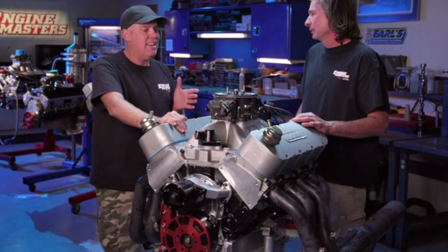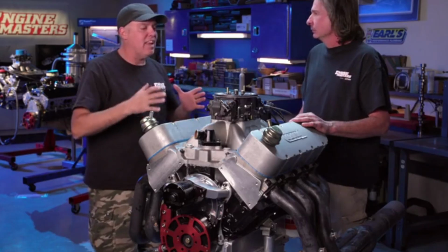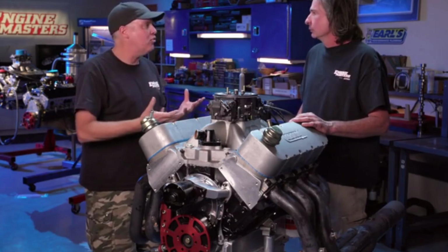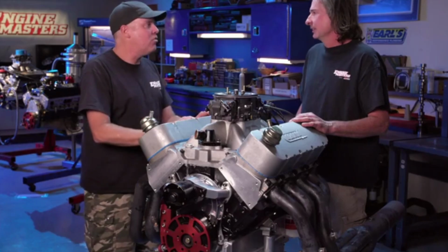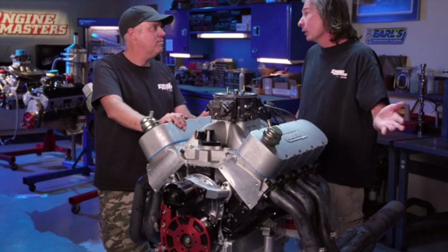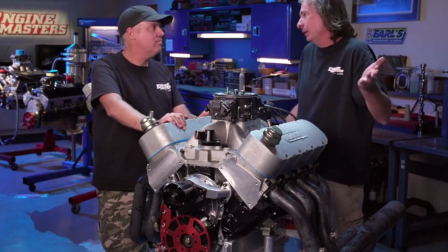Okay, so here's my ultimate conclusion. And I'm going to narrow it a little bit and say, for typical engines within the world of the stuff we can accomplish, meaning not F1 stuff, not even NASCAR stuff, but engines under 8,000 RPM, whether they're race or street, here it comes: rod ratio does not matter. You know, I'll tend to agree with that. Okay. Within the normal range. I mean, if you go super, super long or incredibly short and do something crazy, well, then it might matter some.